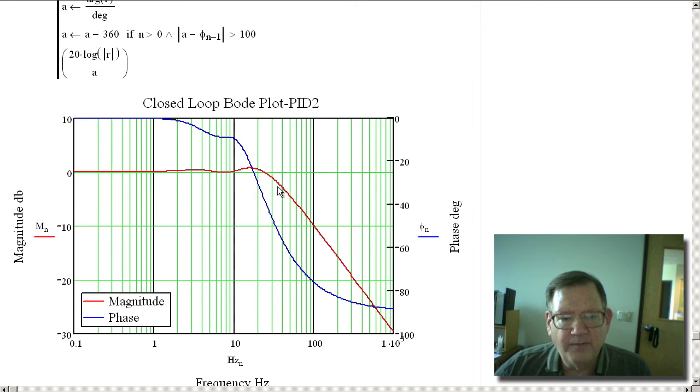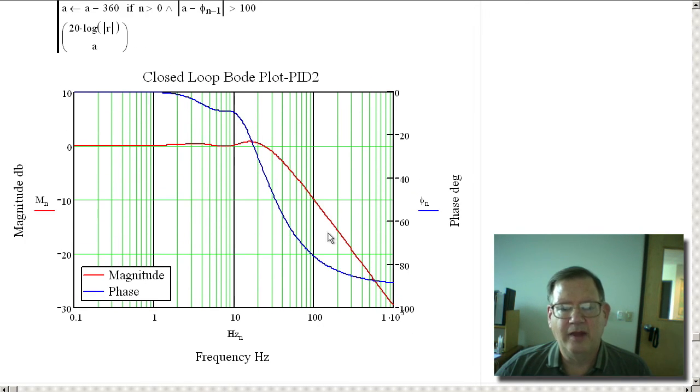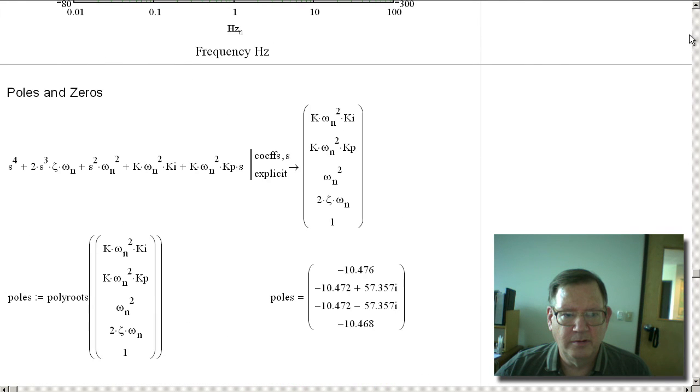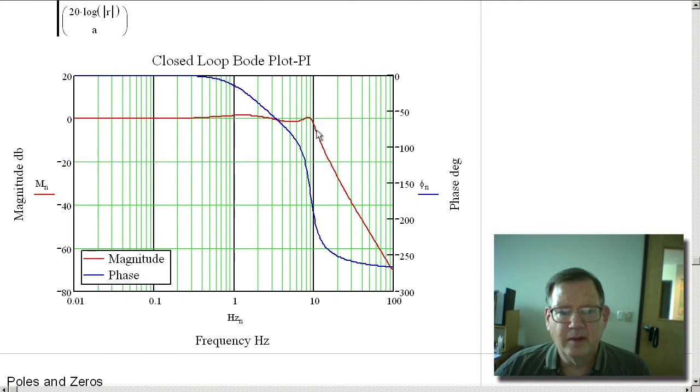That's 20, 30, 40, about 40 hertz. Whereas above, that might be minus 3 dB here. You see, this is a different scale. So that might be 3 dB, it might be limited to 10 hertz here. So the second derivative gain is extending the bandwidth by quite a bit.